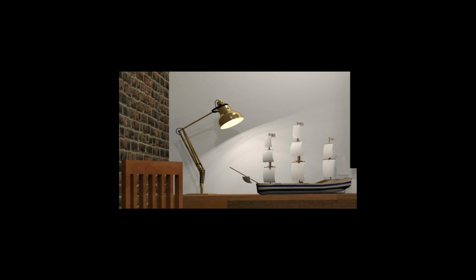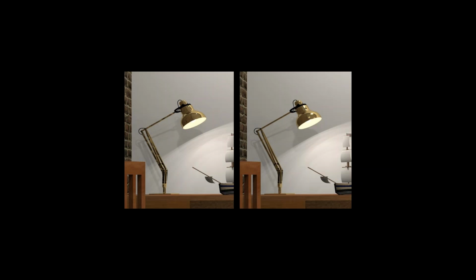In this example, I lowered the sharpness of the reflection to make the lamp look less polished. So I started with the metallic preset, an intensity of 0.9 for reflection and highlighting, and a sharpness value of 1, which makes this metal very polished. And then I decided that I wanted to see this lamp also not quite so polished, so I lowered the sharpness value to 0.6.